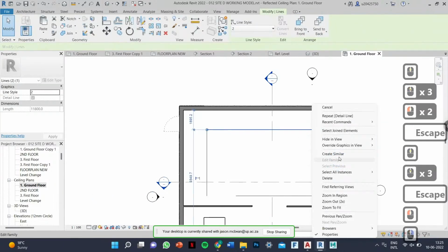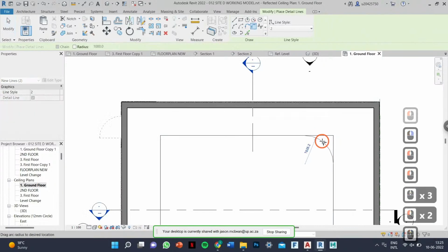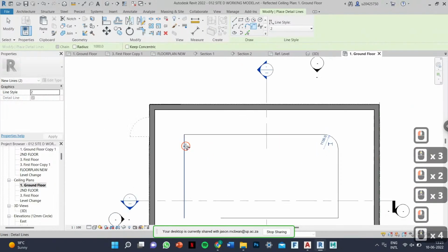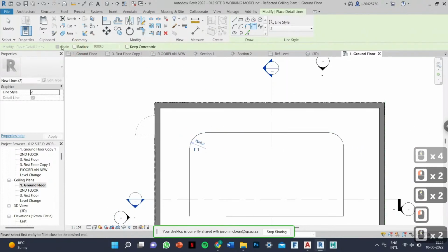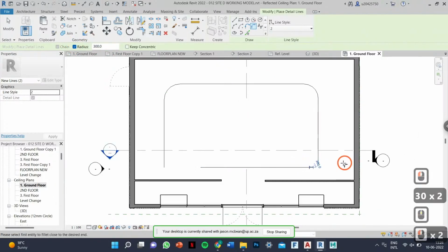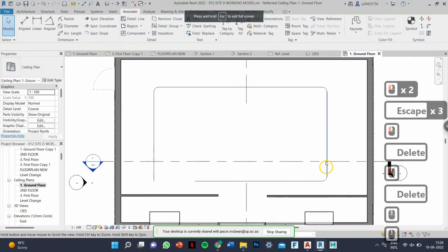Watch this, recreate similar. Arc tool, watch this is so quick. So say now these bends are all the same radius. You can set the radius here to 300, for example. Now, you need to offset this either side by a certain amount.